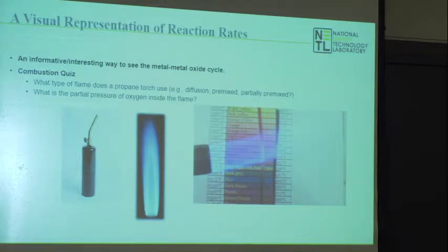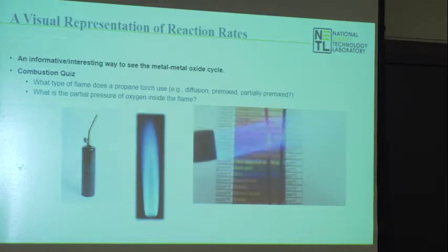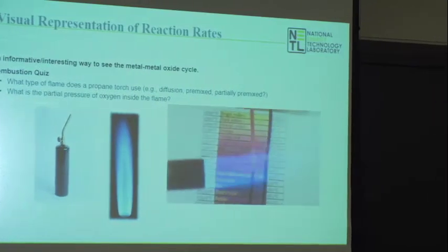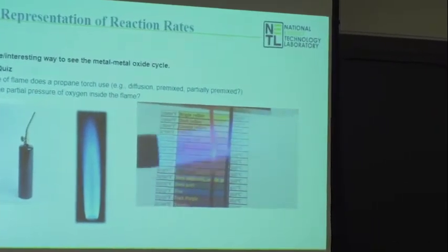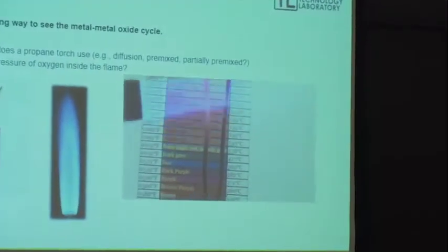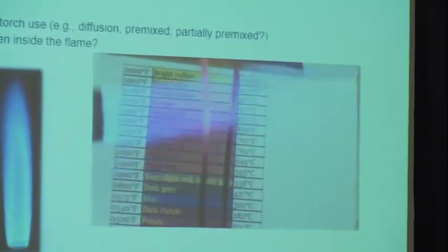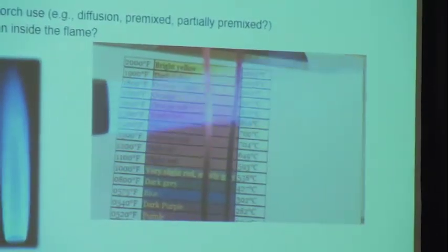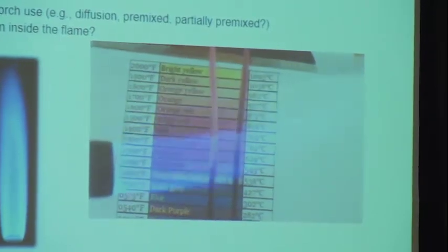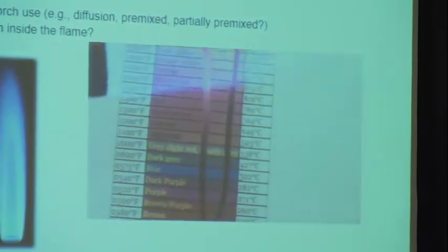So when you look at this, it's really quite instructive. Watch the image there of the flame playing around on the surface. You can see the difference in color right on the surface of the copper. It's shiny in that reducing region, and as it moves around, it oxidizes where it hits the air, right? It turns to a darker color.